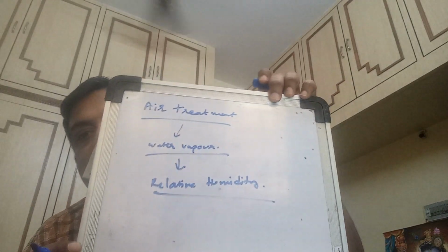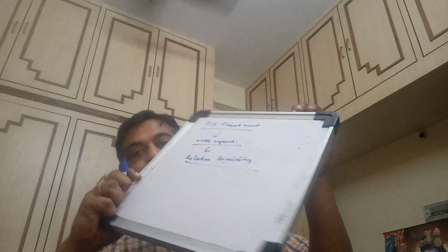The concept of relative humidity talks about the amount of water vapor held in a given volume, and any excess condenses out as liquid droplets. A similar effect occurs as compressed air is cooled, and if left, the resultant water droplets would cause valves to jam. So the thing is air treatment.